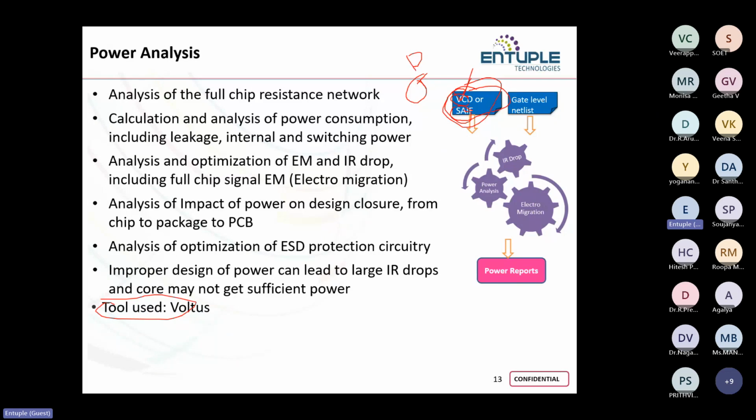Inside an always statement in our RTL code, many signals are called. In a sensitivity list, if something changes in one signal, all signals update. Each and every signal switches from 0 to 1, 1 to 0, and how fast it is, based on that we dump the files into VCD, and then that file is read by the power related tools, which read the switching activity and calculate. So it's all calculation only, not real power from the simulation. SAIF, the switching activity information file, is equivalent to the VCD file.